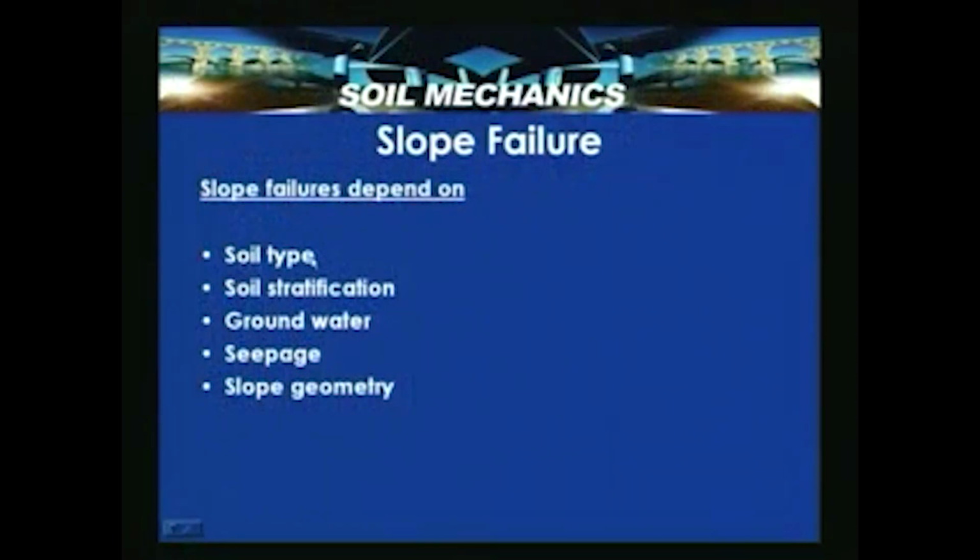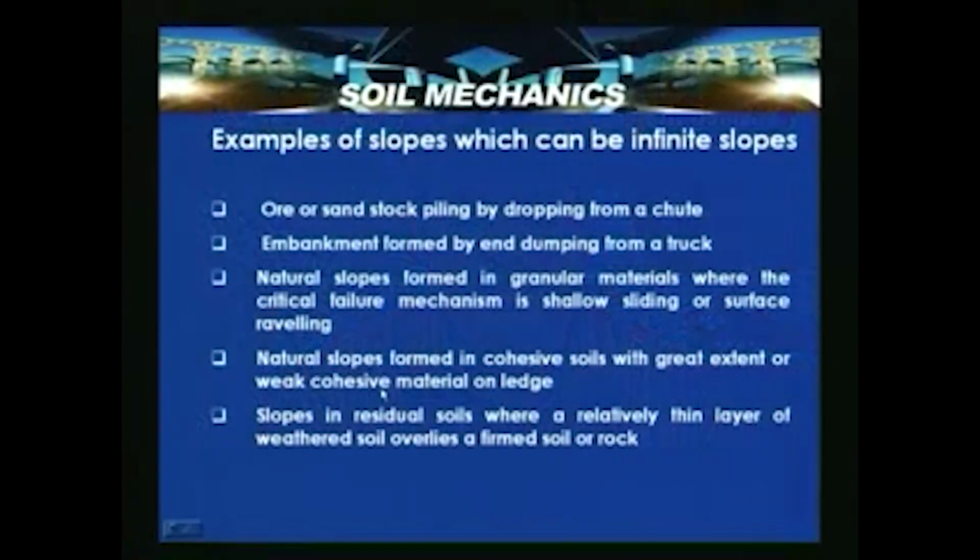So, slope failures depend on soil type, soil stratification, groundwater, seepage and slope geometry. These things are very important. Slope geometry means the steepness of a particular slope. So, soil type, soil stratification, groundwater, seepage and slope geometry.